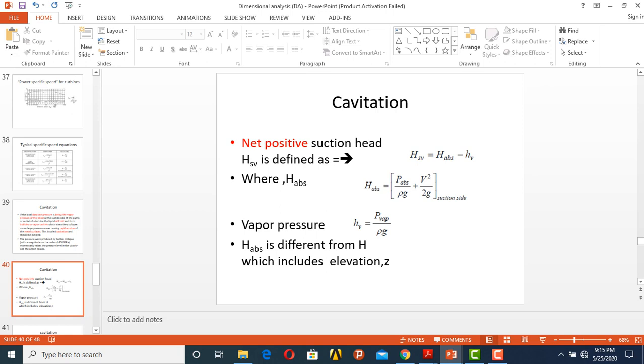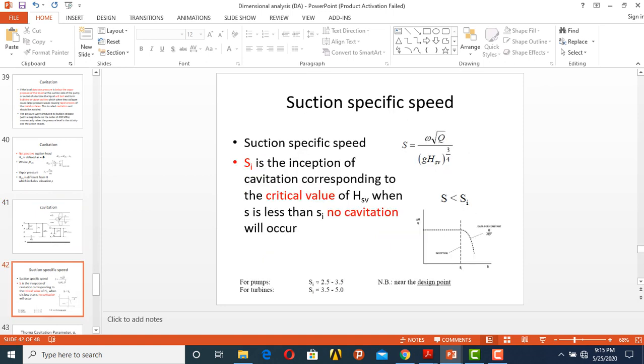The absolute pressure comprises the atmospheric pressure and also the dynamic pressure. Dynamic pressure, in this case, refers to the losses which come about as a result of flow, because those losses are anchored on the flow speed. So when you take these into account, you come up with the absolute pressure, and then this is just the vapor pressure.